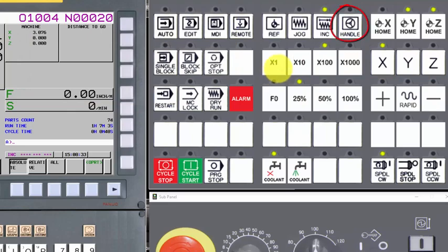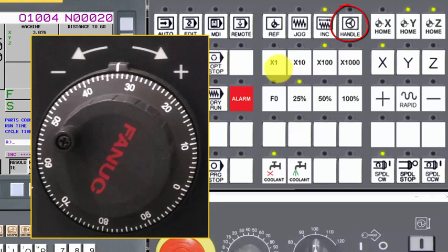Handle mode is the optimum tool to move the axis manually. A hand wheel has a number of graduations and may provide an audible click for each increment of the graduation. The distance the axis moves for each increment or click can also be set with the increment buttons. So with a large increment selected, the axis will move fast as the hand wheel is turned. With a small increment set, the axis will move very slow, providing the fine adjustment required for precise and safe setup. If available, most machines will only have a single hand wheel.